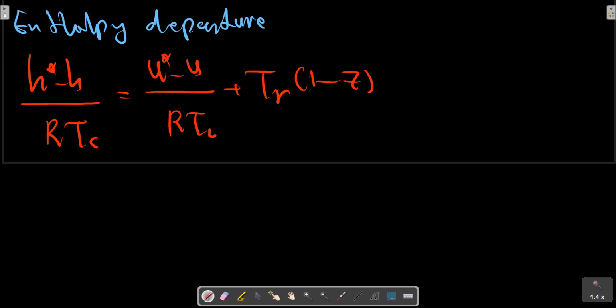Following the same procedure as for the compressibility factor, we can evaluate this equation with a set of Lee-Kessler simple fluid constants to give a simple fluid enthalpy departure. The values for the enthalpy departure are shown graphically in figure D2. The use of the enthalpy departure function is illustrated in examples available in the chapter.